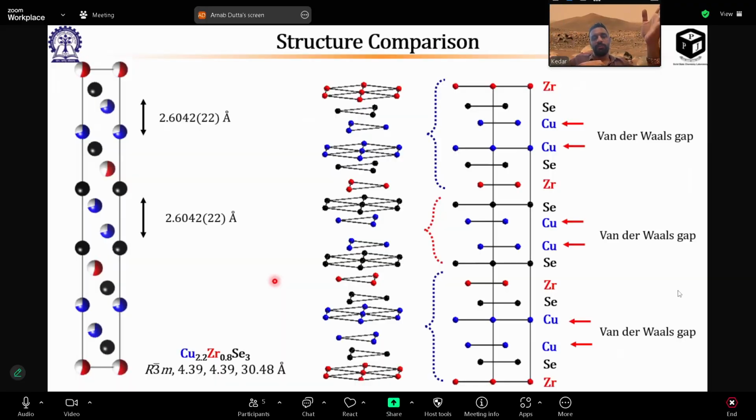In thermoelectrics, one of the more famous compounds is germanium telluride. I think it's cubic, or I forgot, rhombohedral at high temperature, and there's a low temperature phase, which has less symmetry. So we thought, if we go to the temperature where we know the cubic phase exists and kinetically freeze it, we should be able to lock the high temperature, high performance phase at room temperature. But we couldn't do it after many, many attempts, and we don't know the reason why. This is where the whole metastability argument started. So I think it's nice that you guys are chatting.